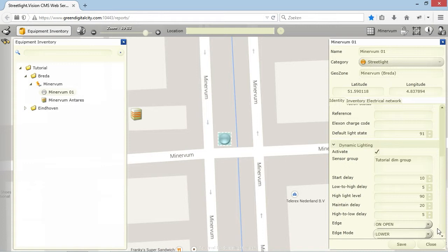For example, if in your schedule the light level is 100 and you have set your trigger light level to 90, that means that this trigger will happen. Now setting it to always means that your trigger will happen at all times. And finally, press save to complete.